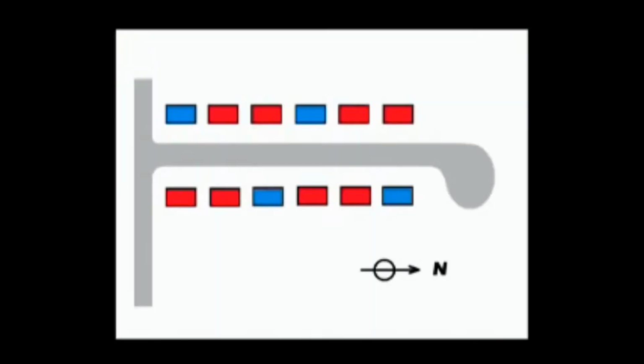Coming back to the site plan, the remaining 8 houses are the experiment group. These crawl spaces were converted to closed crawl spaces for the field study. We did this by carefully air sealing the exterior walls of the crawl space. In this shot, you can see workers using rigid pink foam board to seal off the foundation vents, as well as the wall hole for the duct connection to the outdoor packaged unit.